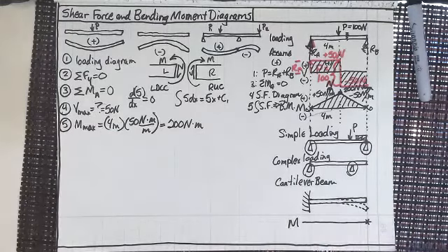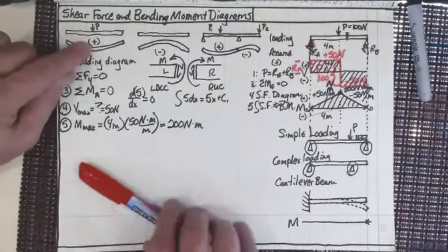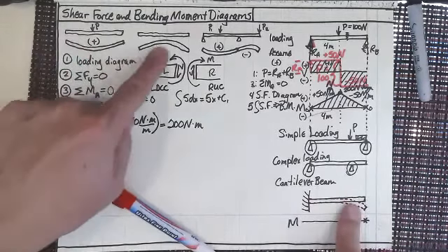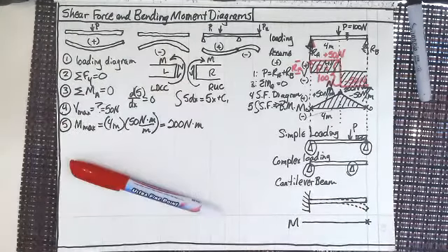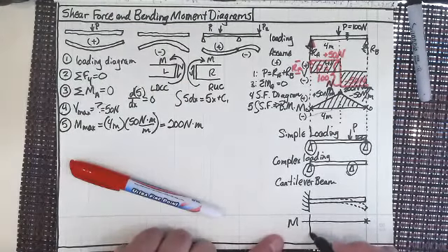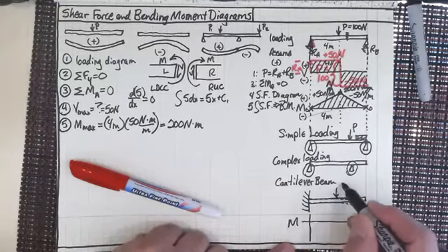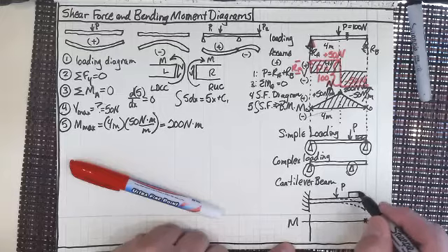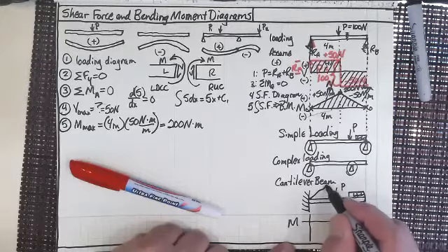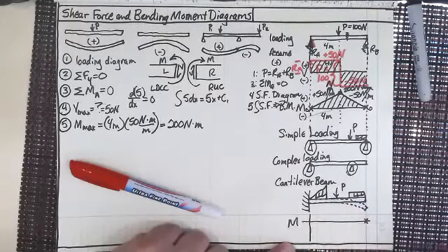Now, is that positive or negative bending? Because I've got the positive one that's bending like this, right? But this isn't. This is bending like that. So when I look at this, if I were to draw my shear force and bending moment diagram, this is all going to be negative, isn't it? Depending upon my load. Let's say that I've got a load P there, and I've got some type of uniform load there, and I've got some other type of non-uniform loading here, right? Something like that, but it's going to bend down.